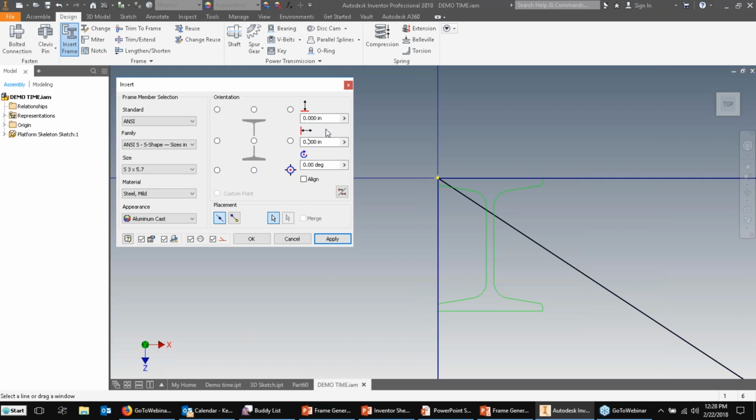So that's what these 2 offset boxes are for. They allow you to control the distance offset inside or outside. The distance can be positive or negative, so you can control that gap. So this gives us our gap space for the 1/8 inch thick sheet metal skirt that we're going to be putting on this. For simplicity's sake, on the edits that are going to come later, I'll just set this back to 0.